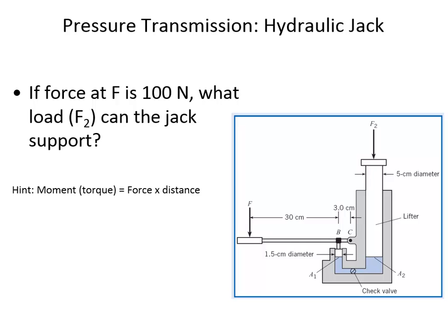Okay, so this area, if we calculate pi d squared divided by 4, that area is 0.0001773 meters squared. And the pressure is 6,225,000 newtons per meter squared. That's 6 megapascals. We better have a pretty good, nice, strong cylinder.